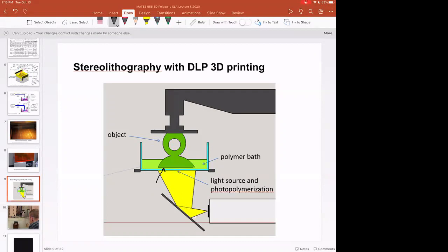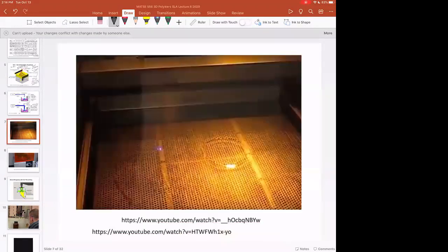That's due in part to the higher viscosity of this polymer bath, in order to break that suction. So you tend to need low viscosity for bottom up DLP, and you can get at higher viscosities with top down. You still need reasonable viscosities, like honey is a maximum viscosity for a lot of these resins, but the viscosity is tuned to the process.